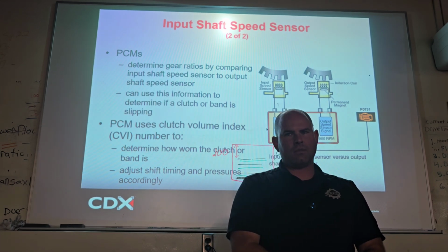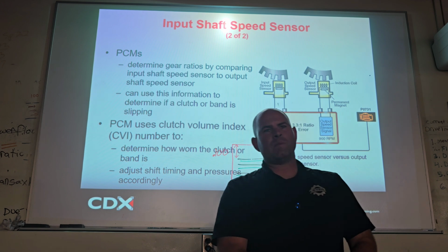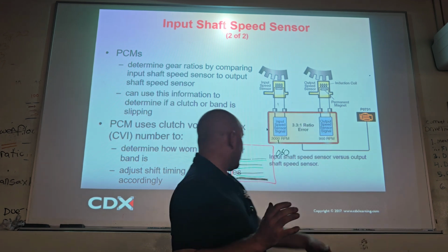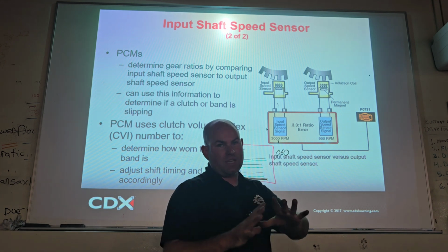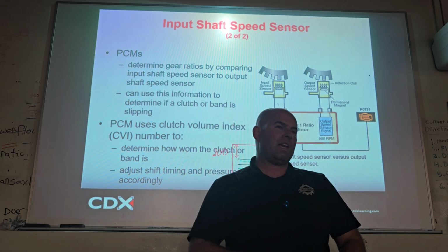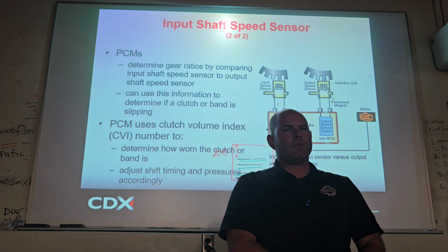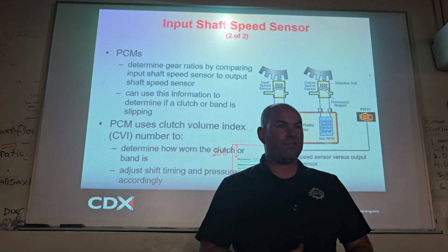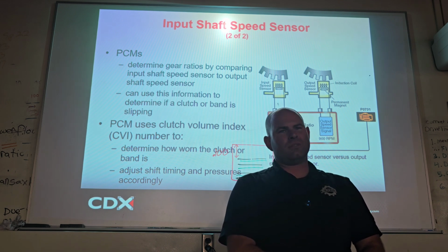Watching this, do you understand? All right, so let's just say, hypothetically, you yank that transmission out of there that had 100, and you slam one in there that has 60, and you don't do anything with the ECM, how are those shifts going to be? They're going to be too fast. They might even feel a little bit harsh. All right, so what do you think the ECU should do?